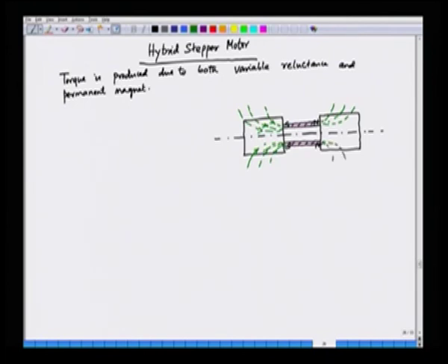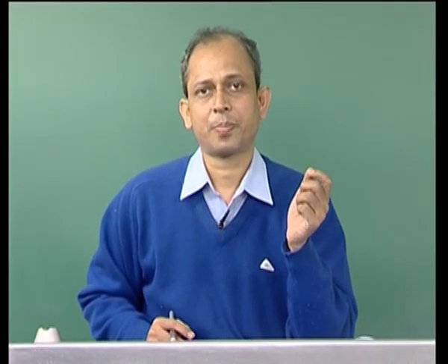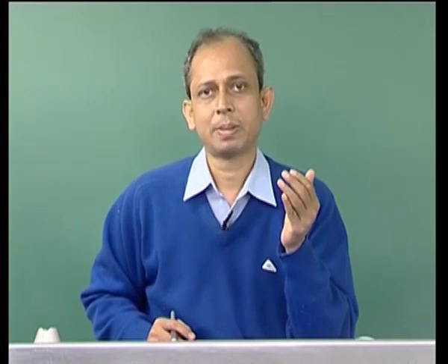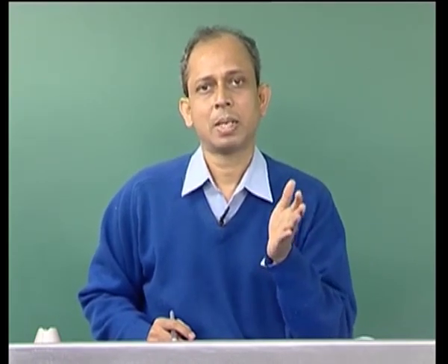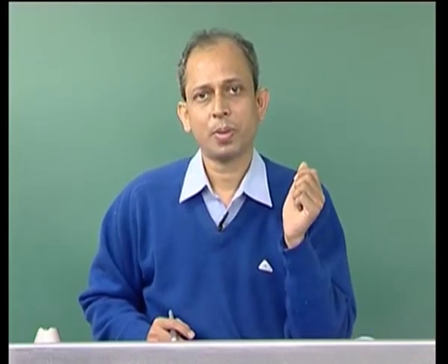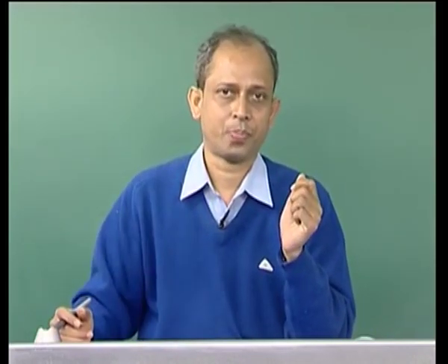This is the north pole structure. The flux is coming out of the north pole like this. As a result, the left side block is completely a south pole structure and the right side block is completely a north pole structure. Now, the advantage here is that we do not have to place tiny permanent magnets. We are just placing one axial magnet in such a fashion that half the side of the rotor is a south pole and half the side of the rotor is a north pole.